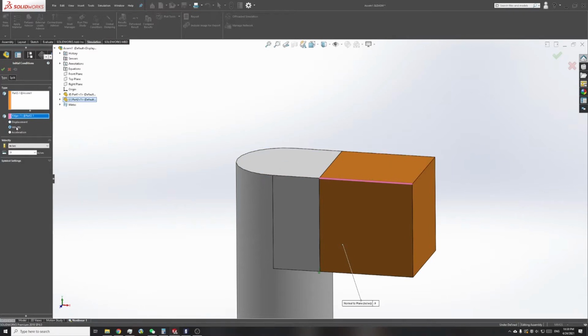So I set an initial velocity of -9. If you set it to 9, you can see the arrow is to the right, but we want it to go left, so we put negative. -9, which means the punch will be at this speed.